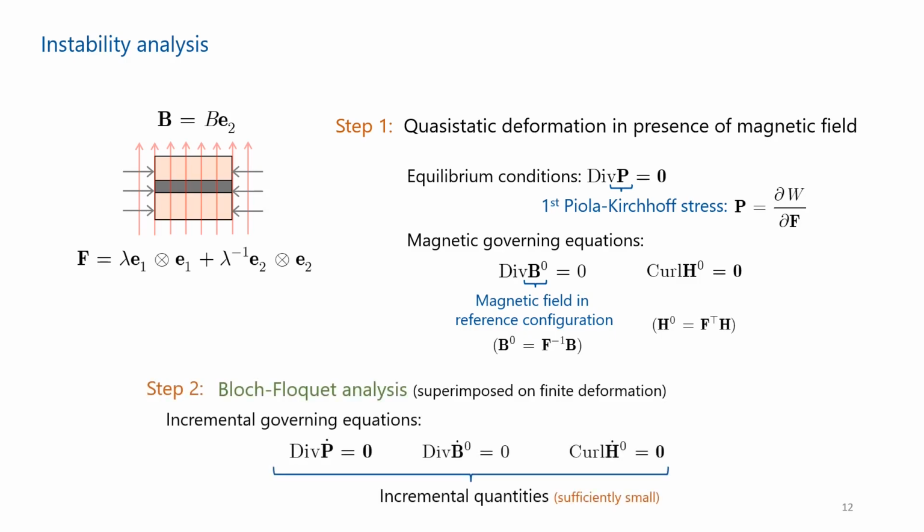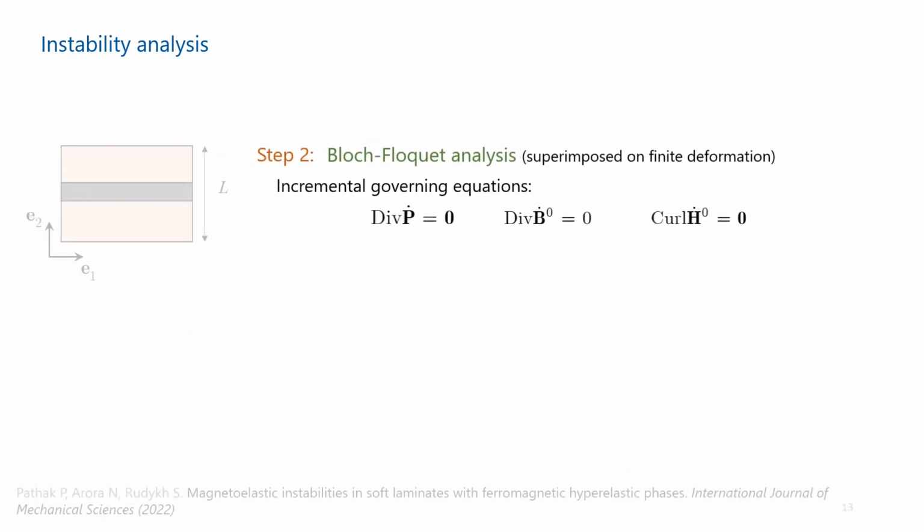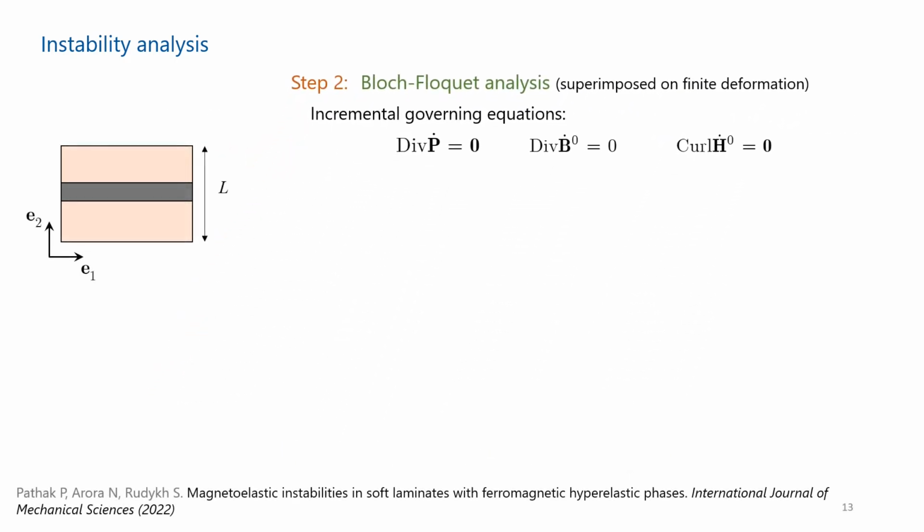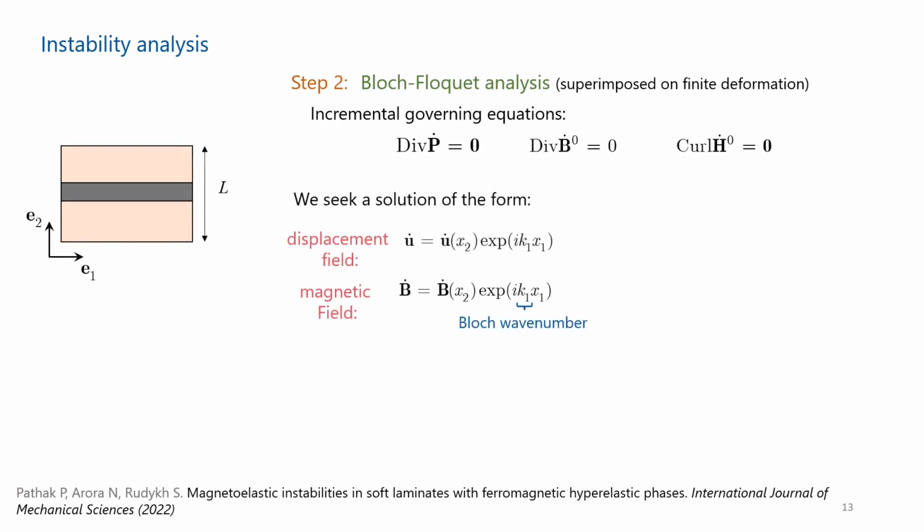Next, we perform the Bloch-Floquet analysis superimposed on the finite deformation. In particular, we perform the incremental linear analysis with the assumption that these incremental quantities are sufficiently small. To this set of incremental governing equations, we seek the incremental field solutions in this form.